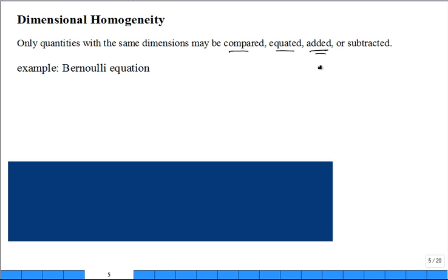It's not expressed right. Examples, Bernoulli's equation. We had the pressure. We had the 1/2 rho v squared. We had the rho gz. All of those add up, and that's a good equation. Each term has to have by itself the same units as the others. Pressure, pressure, pressure. We gave this a name. This was called the velocity pressure or dynamic pressure. This was given a name.